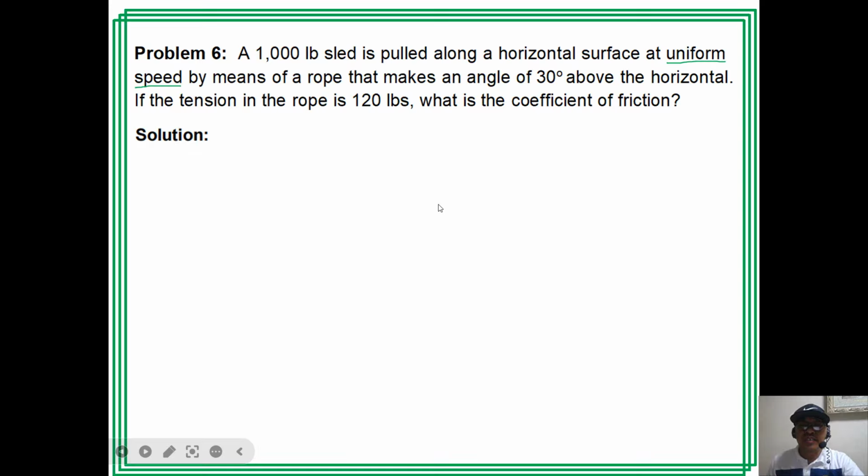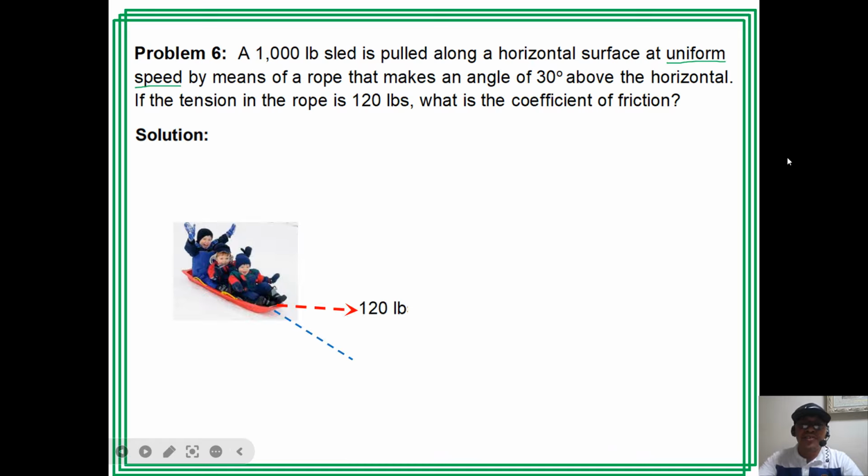So there is a resultant force on the forces acting on the body. So that is not balanced. That is why the body is moving with acceleration. So that is our next topic, Newton's second law and D'Alembert's principle. We have the reversed effective force. Okay. So again, although this is moving, but moving with uniform speed, we can directly apply our static equations.